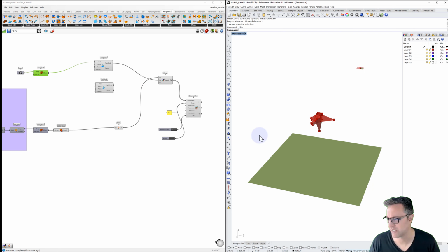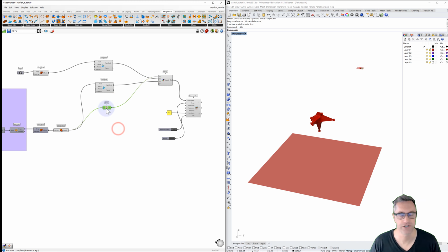Doesn't look like those are lining up, so we'll see if that's a problem in a minute. But our union mesh is also going to be a rigid body. We'll plug that into part. We'll pull the rigid body out and plug that into the merge. We have our show. And then we need two more things. We have to add a load, and then we have to do one other element, which is the solid plane collide.